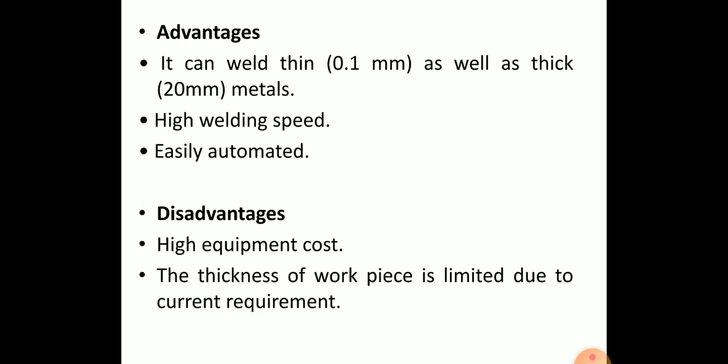Then the disadvantages: high equipment cost. The thickness of the workpiece is limited due to the current required. Another is that certain resistance welding operations are limited only to lap joints. Skilled persons are needed for maintenance. Bigger job thickness cannot be welded.